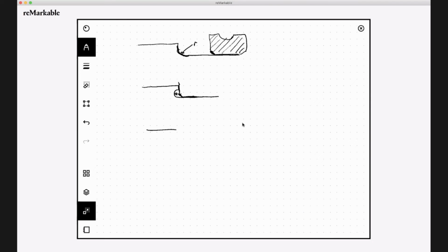Or you can have what's called a stress relief groove, which is actually cut into the back of the shoulder. That has the effect of smoothing out the stress because it's starting to move it away from the shoulder a bit further back, which is only a very arm-wavy answer, but you can do that. Or the other thing you can do is potentially put in a spacer ring.